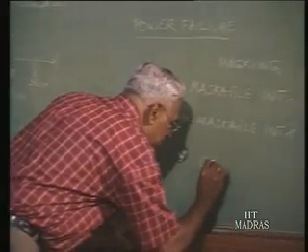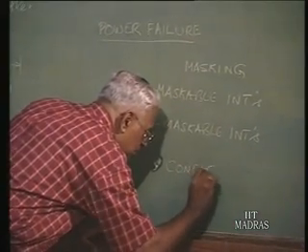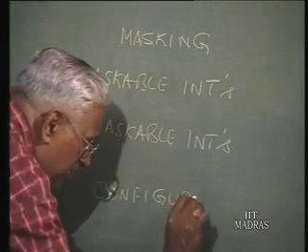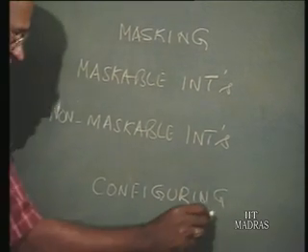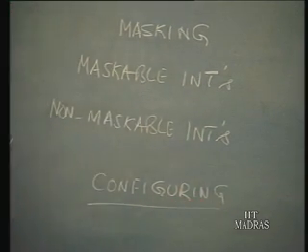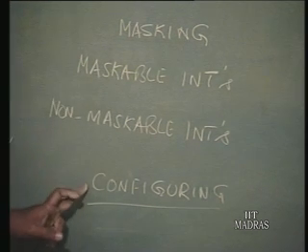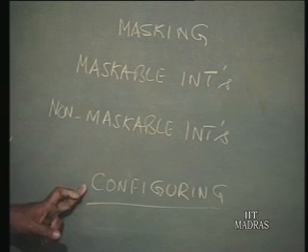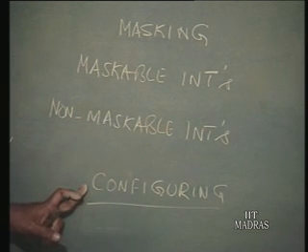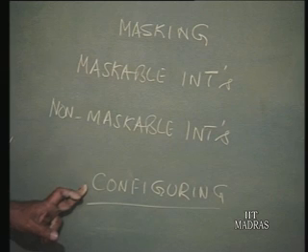Earlier, remember, we were talking in terms of peripherals, we talked about configuring and then data transferring, that is the configuration phase. So, selectively masking any interrupt; non-maskable you just cannot do anything, whenever an input comes on a non-maskable interrupt, it will be responded to by the CPU.